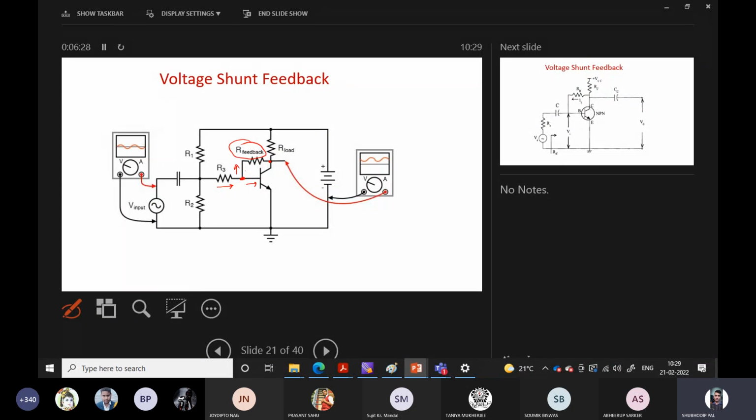So whenever the current is taking two paths, what does it indicate? Voltage divider. Shunt, it is connected in parallel. Yes, that means it is parallel. So try to understand the series and shunt configuration. A shunt configuration, that is parallel configuration, means the current takes two paths from a common node, so the current is divided into two paths here.